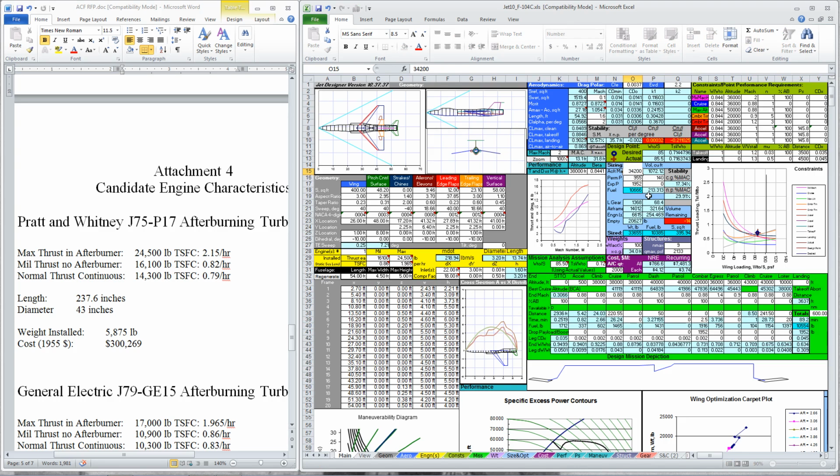34,200. Okay, and we still need some cubic feet here, so we'll add those cubic feet in ahead. Let's go 5.3 for width. And I have an idea. You see how the F-104's fuselage at the rear of the cockpit there at about 17 feet. Next back down, I'm thinking we're going to keep that longer, but there's a fuel tank right there. We're just going to make it a bigger fuel tank. So it's right at about 16.2 feet. It's 6 feet high. Let's just keep it 6 feet high for a little while, and I'll bet we get our volume back pretty fast.